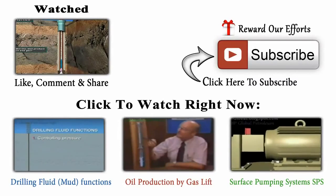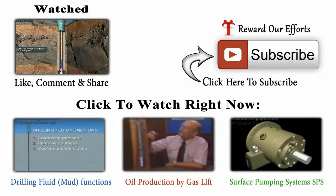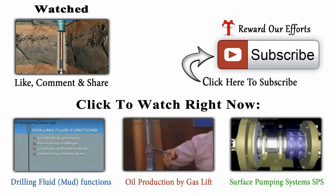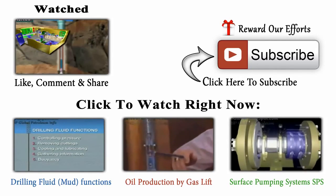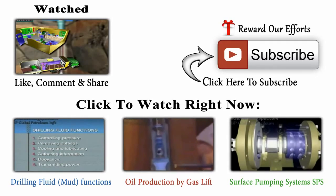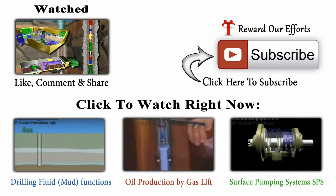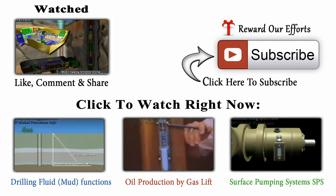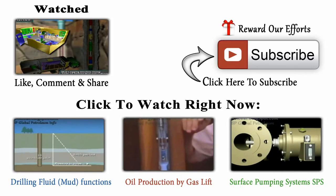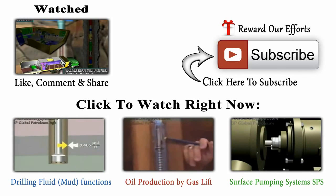Often faced by the well owner is the question: will this well produce oil and gas? To help answer this question, one or more methods of evaluation are used, including mud logging, well logging, and drill stem testing, or DST. Mud logging involves doing tests on the drilling mud and cuttings circulated out of the hole. Well logging is the recording of information about subsurface geologic formations,